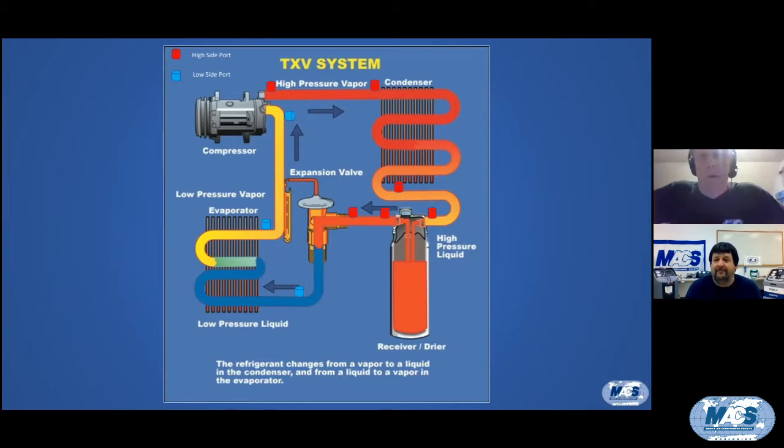Well, in theory, those pressures really aren't going to be the same at every place in the low side. When you start moving a liquid or a gas through piping and so forth, the further that you get from the point where it's being pumped, the lower that the pressure is going to be. Now, it would take a gauge, probably graduated in tenths of a PSI, to see some of this, but just to give you a good example of how you can get pressure drops.